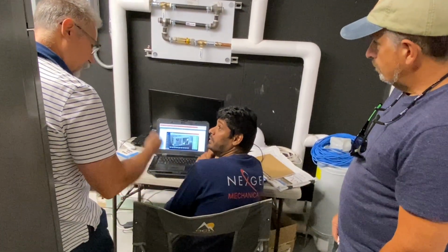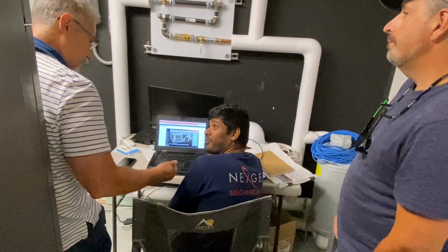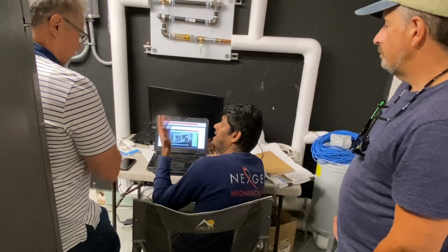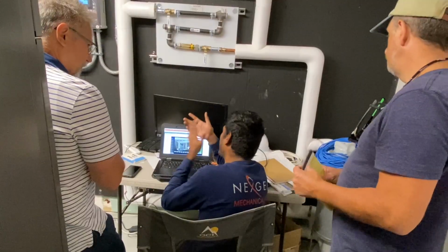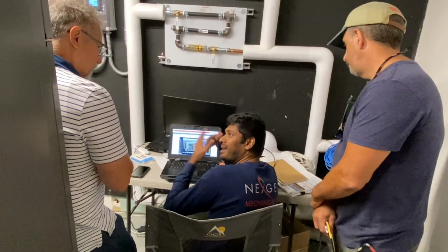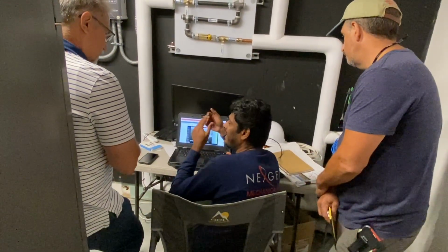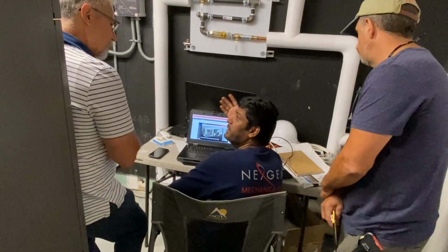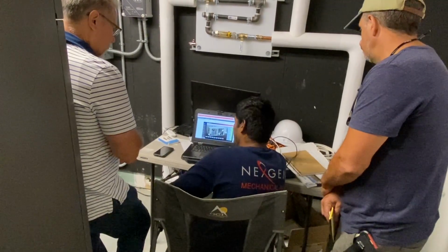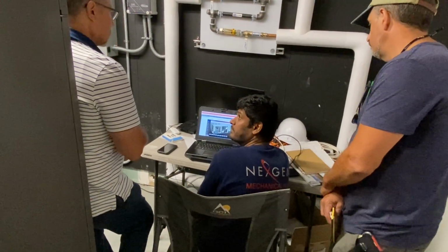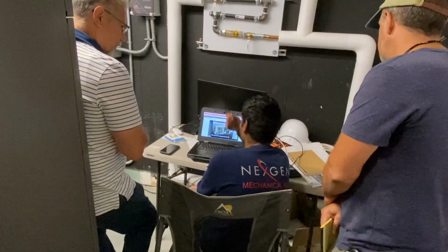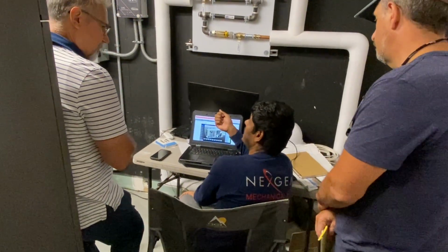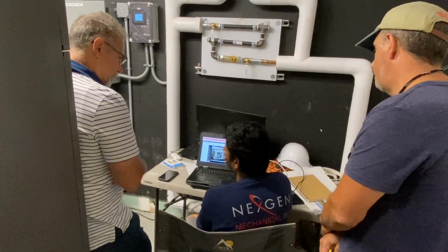Yeah, I was using an example of 5, so 3 was over 50%. Okay. You're using all 20. I get it. I understand. So right now we are still tweaking the reset range, between 55 and 62, but the cool down mode is going to give a constant 55, and the warm up mode is going to give a constant 80. That is again adjustable. Right. And we talked about the discharge air, and of course it's going to control the DP.